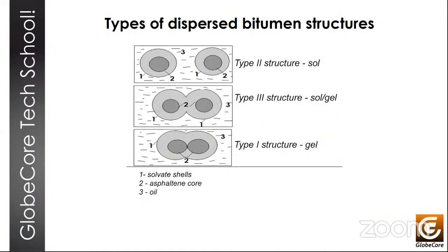So the composition of polymer modified bitumen includes viscous road bitumen, a polymer, and a plasticizer. Therefore, a change in the quality and quantity of one of the components inevitably brings about a change in the quality of PMB. And PMB is a polymer modified bitumen. Studies have found that the properties of PMB depend on the properties of its ingredients, while the type of dispersed structure of bitumen has the most significant effect on the properties of the material.